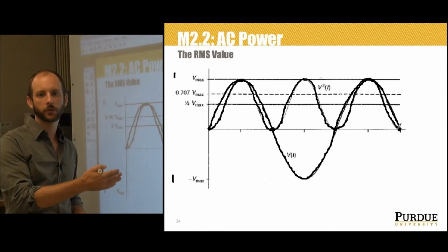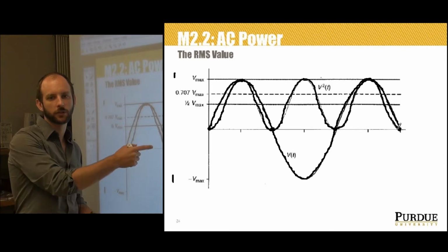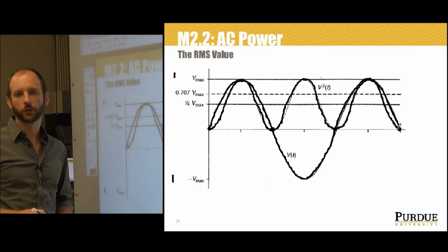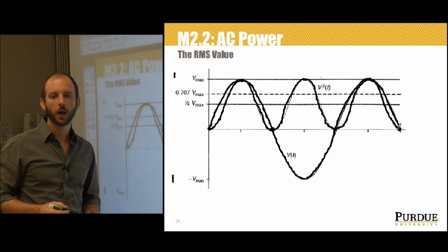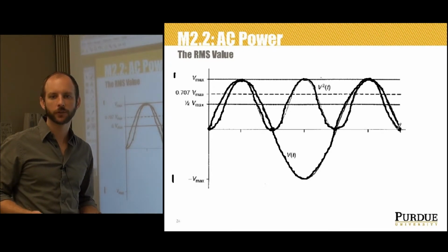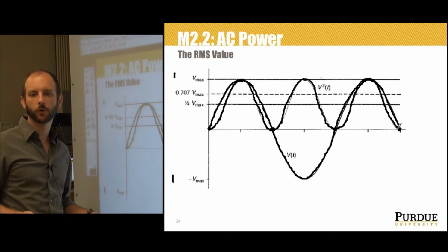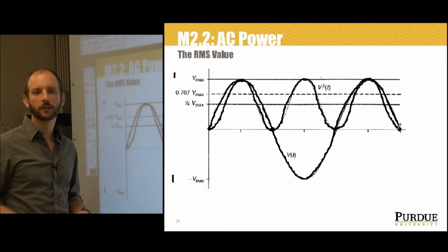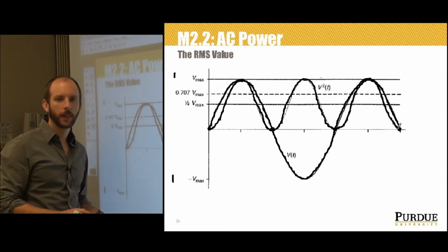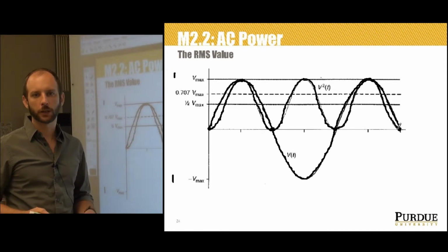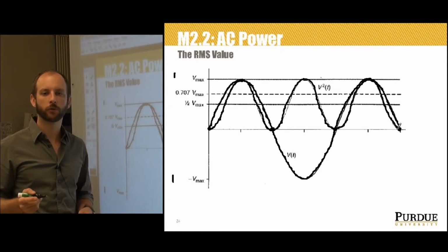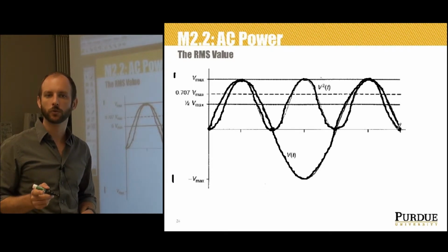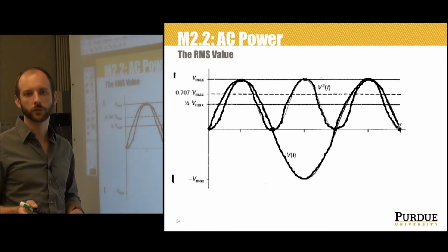What we would like to do is have some method of averaging this periodic voltage and current that offers a good representation of how much current or voltage is actually being supplied. A meaningful measure, something that allows us to compare between periodic AC waveforms of different shapes and DC voltages and currents. And put this way, the answer almost becomes obvious. What we really are interested in is comparing different waveforms based on their ability to do useful work when applied to a load resistance.